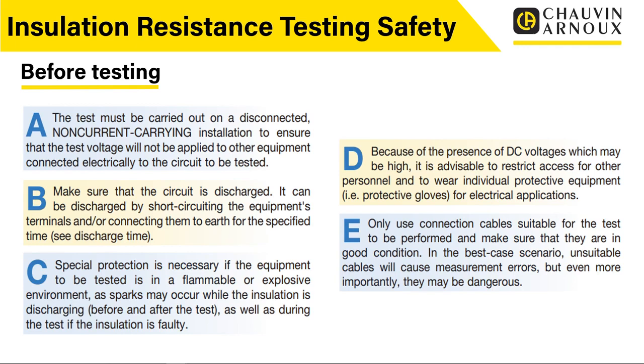This is a dead test, for want of a better term. It's not carried out on an installation that's connected to its supply. It is not a live test, it is a dead test. So B, make sure that the circuit is discharged. It can be discharged by short-circuiting the equipment's terminals and or connecting them to earth for a specified time.